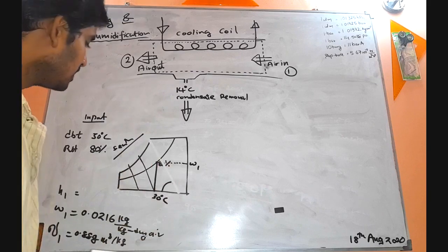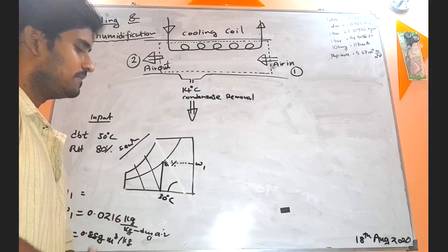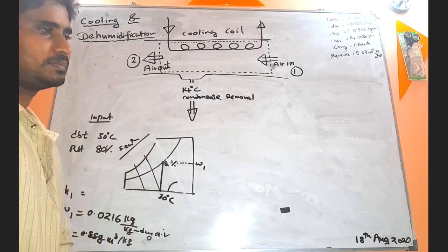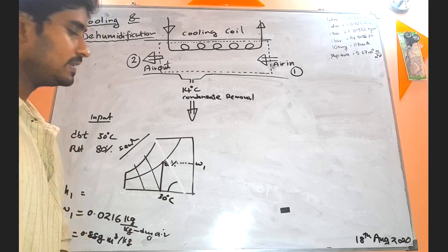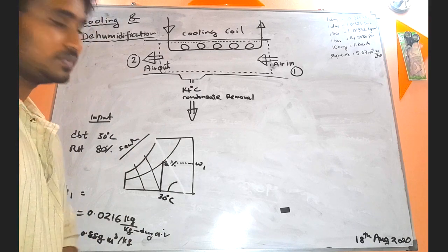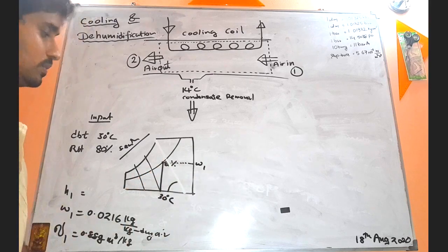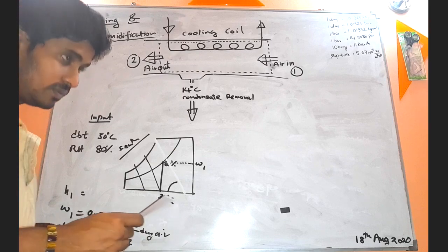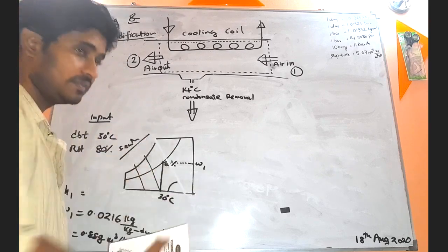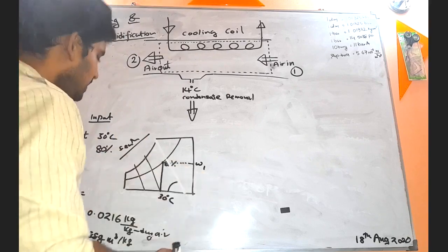If you consider one line that represents the wet bulb temperature, it makes an inclination of roughly 25 to 30 degrees with the left horizontal. So there also, if there is no specified line that exactly passes through the point of intersection, then you have to follow the pattern. Shall I draw it here again?